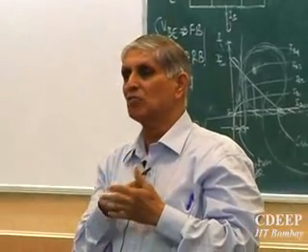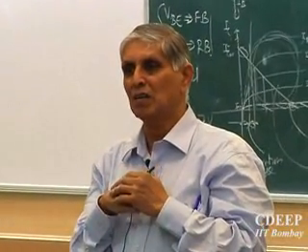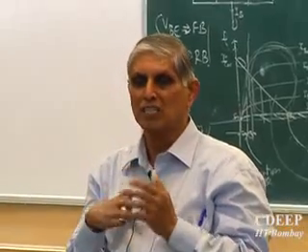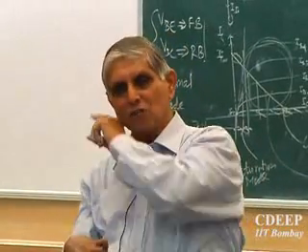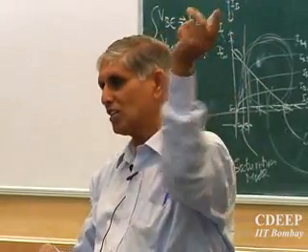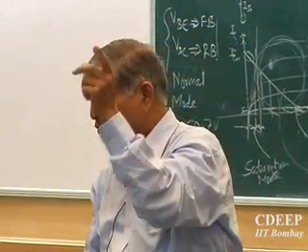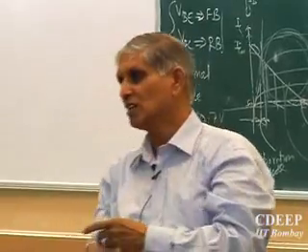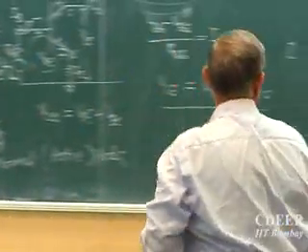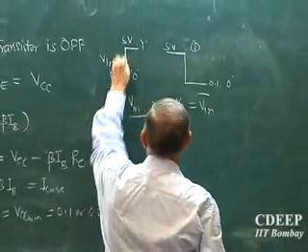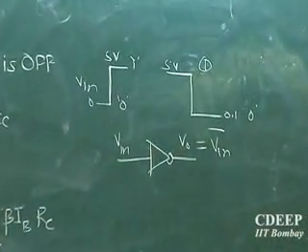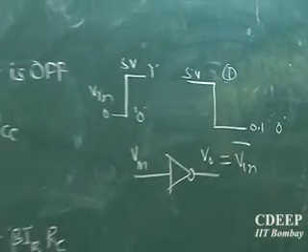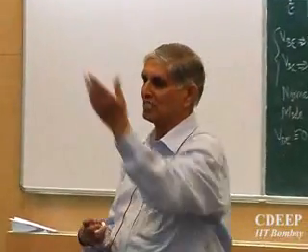For an analog circuit, we'll always put the device in active mode, and in digital, when you apply pulses, it will always go from cutoff to saturated and saturated to cutoff, though it will traverse through active mode both ways. The only reason we don't calculate it is that this time taken is practically very small, as small as possible. We want probably 0 if you wish, but it may have finite time. That is what the speed of an inverter will decide, how fast this can transmit. Is that clear?